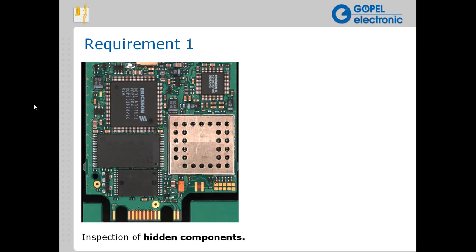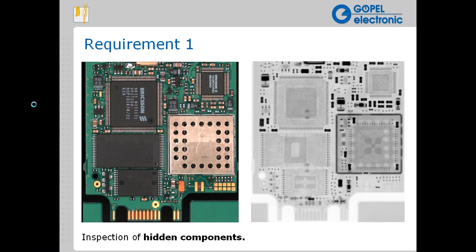For a second example of a requirement, which involves hidden solder joints. In this particular AOI image, as you can see in the center of the image, there are 4 FPGAs. And of course, from an optical standpoint, the connections for those BGAs are not visible at all. Even from angle view, those aren't visible.